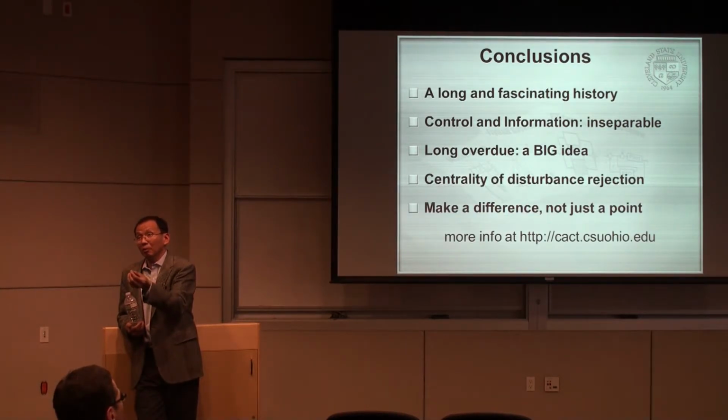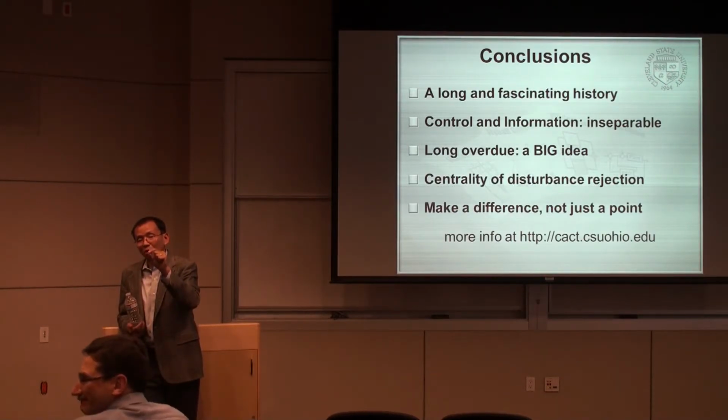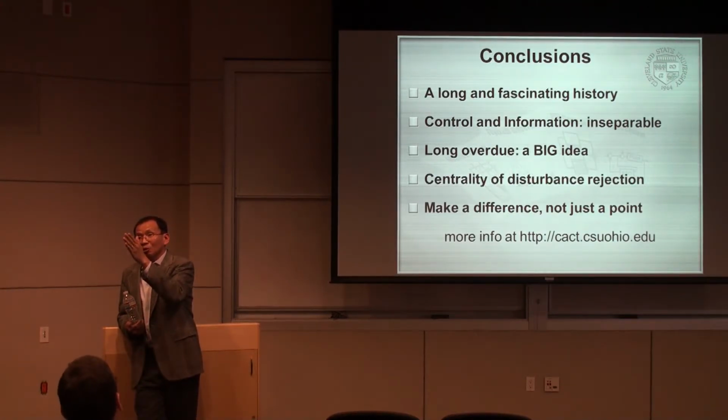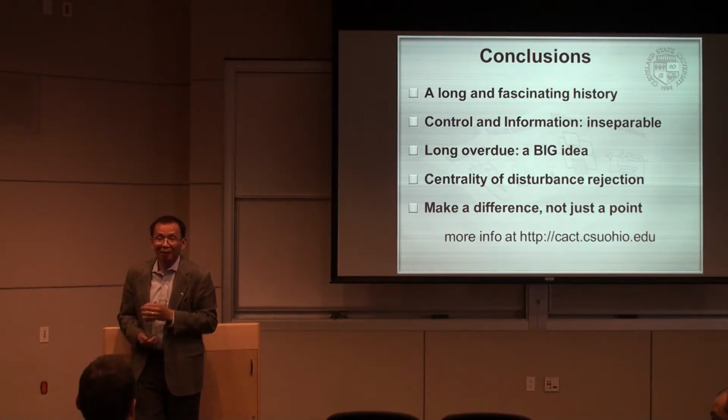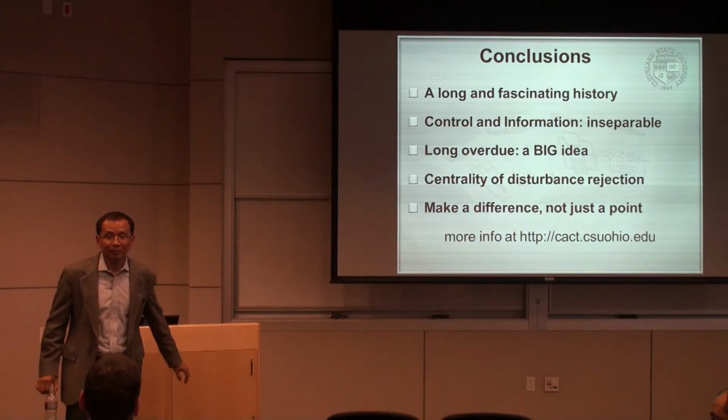Yeah, I understand. So if I may, maybe the model we're using is y double dot equals u. That's an ideal integral plant, a pure integral plant. And we're treating anything away from that as the f, estimated and cancelled out. It doesn't seem completely true, because for oscillations, you seem to take a more detailed model of the plant.